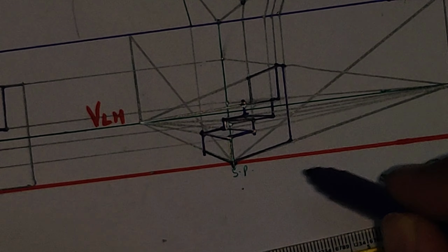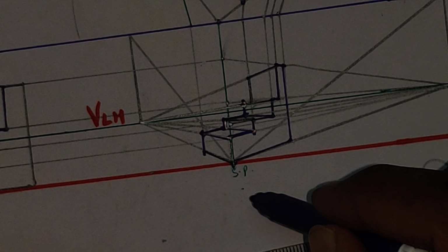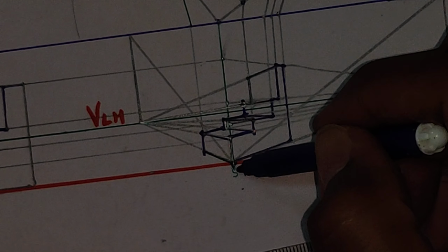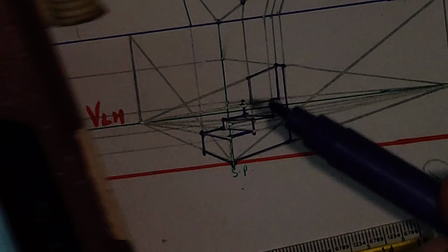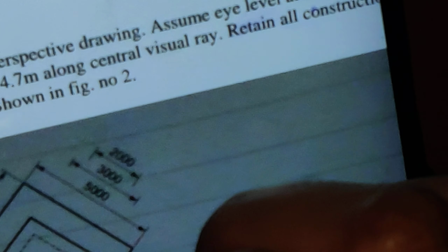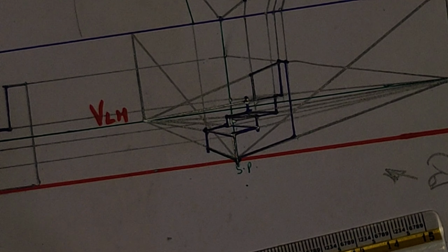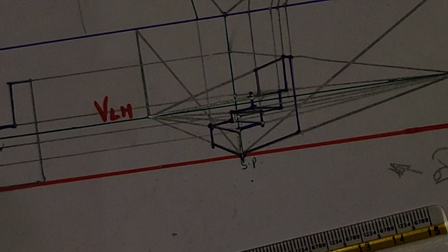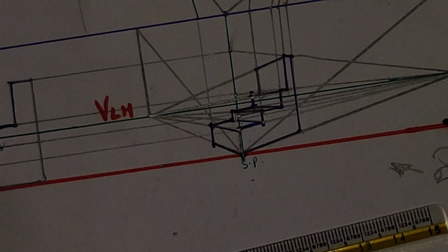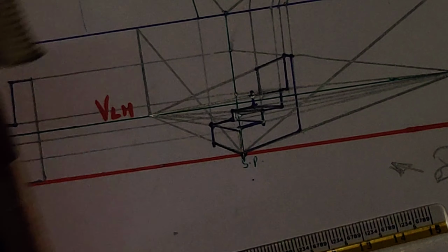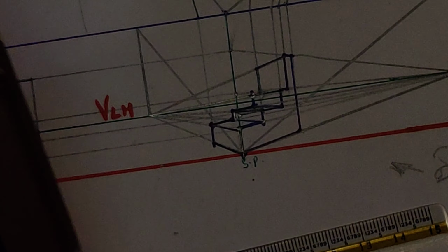In this question the station point distance is not given, so we have directly taken that point here. And in addition to that, eye level is at 2.1 meter above the ground level. Means eye level जो भी है वो यहाँ से 2.1 मीटर above the ground level है, राइट? तो इस तरह आपको ये जो ड्राइंग रहेगा ना, इसके लिए प्रोसीड करने का है.